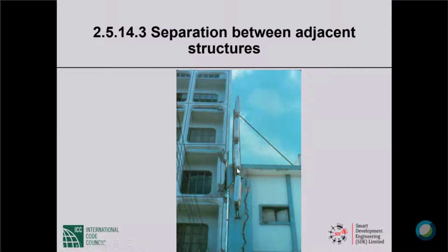And that is a very, very bad situation. In this case, there is very major damage. I don't know if you see the shorter building and the taller building, it is not very visible, but this is a dangerous situation. If the floor hammers against, let us say, the mid-height of the column, sooner or later the column is liable to give.